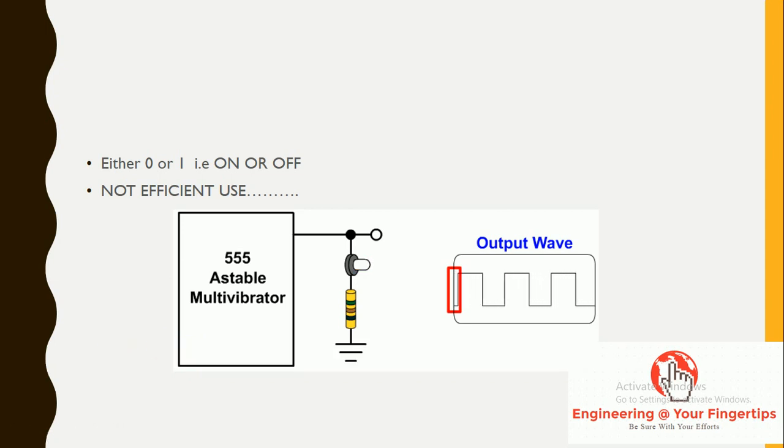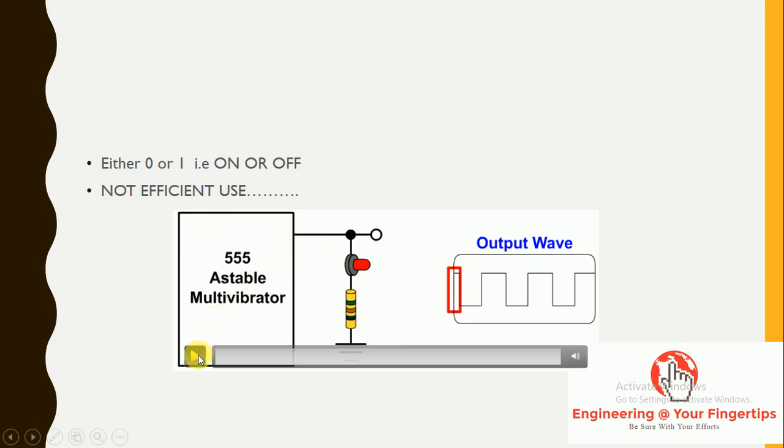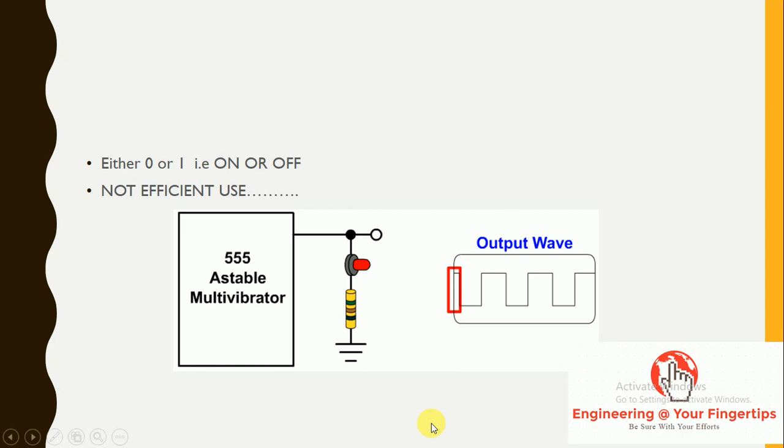Now this is for complicated actuators. For complicated actuators, this doesn't use the full potential of the actuator, meaning like with a monitor you can put up messages, draw pictures, all kinds of sophisticated things. But if you are doing on off actuation, all you can do is turn it off and on. So you are controlling it, but in a minimal way. With an LED, off and on is often enough, but you could make it dimmer or brighter. But with on off actuation, that is not possible. So this is one way to control an actuator, just throw power.